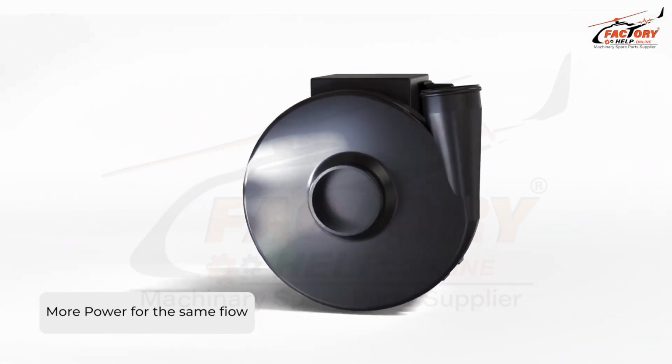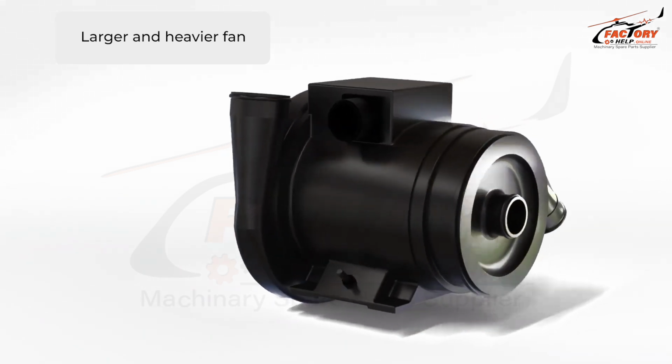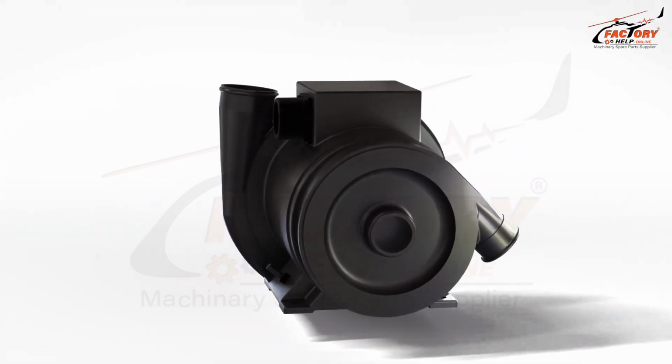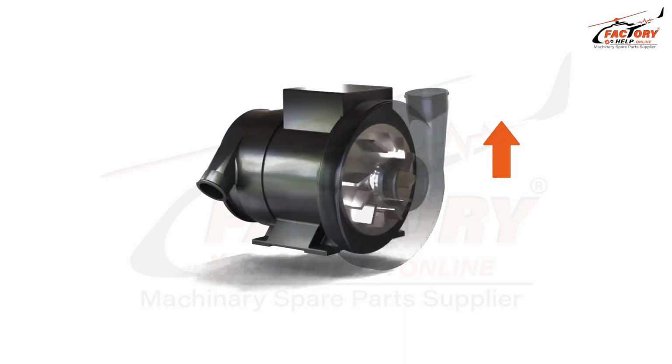A centrifugal fan works using a different set of principles. Air is drawn into the fan axially and exits radially. Air trapped between the fan blades and the fan's outer casing or scroll is thrown out radially when the fan is spinning. The exiting air volume leaves a vacuum, drawing in a new packet of air to replace it. The air flows around the curved walls of the scroll, and the air exhausts radially because they use centrifugal force rather than an aerodynamically efficient airfoil blade.